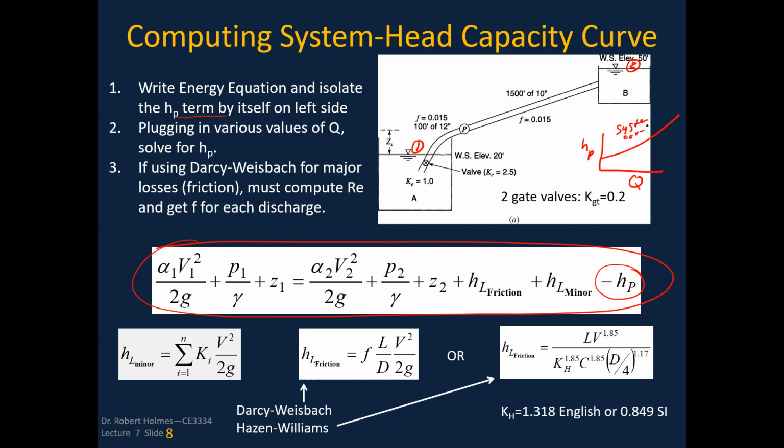It's a fairly straightforward concept. Saying that it's simple would give a false sense of security, because I know students sometimes struggle with this, but it is not that difficult as long as you follow the first principles: writing that energy equation from one location to the other through the pump, making sure that you're including the pump, the friction losses, and the minor losses.